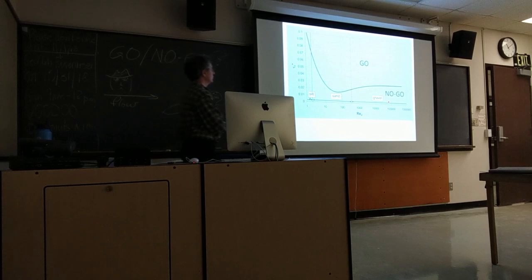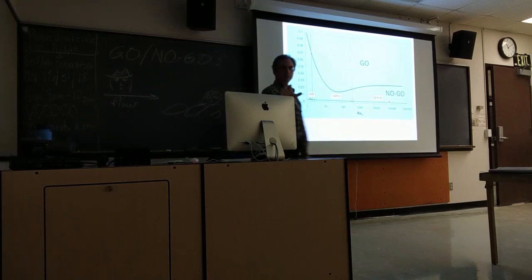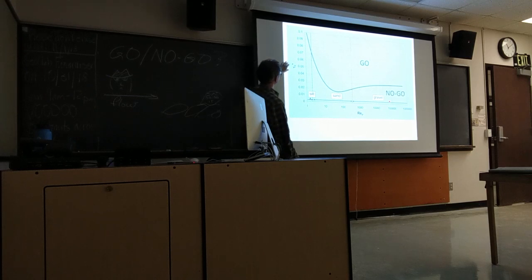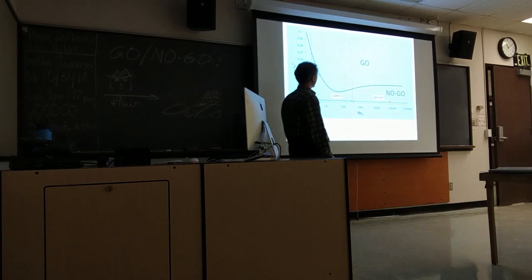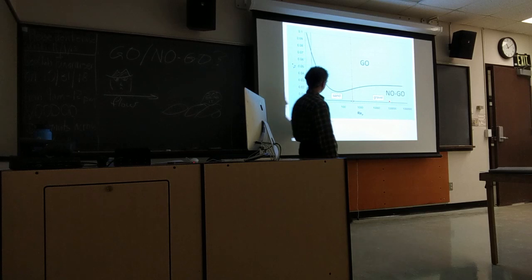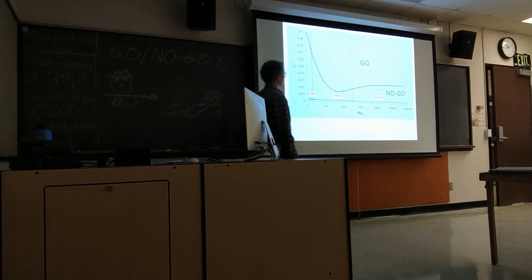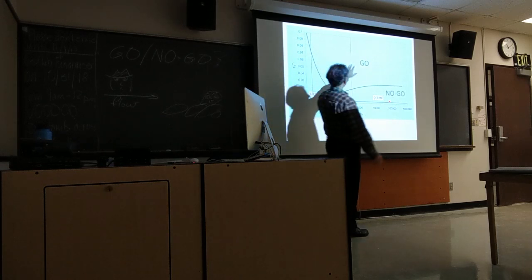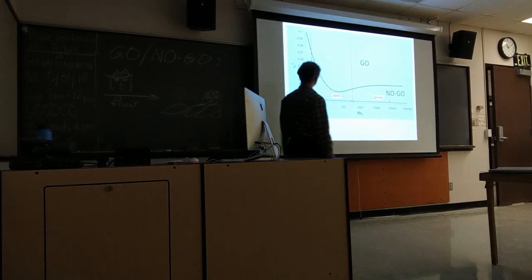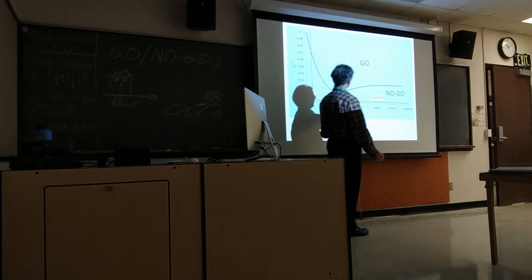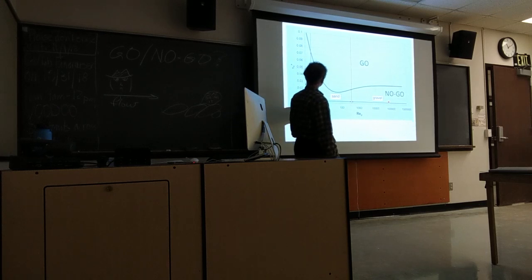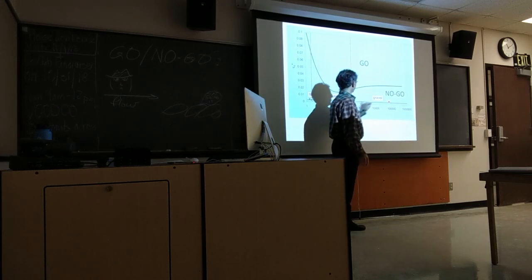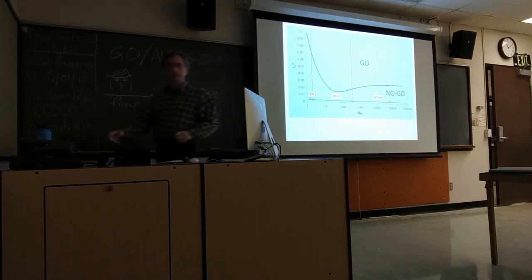This is a modified Shields diagram. And here we see this is labeled tau c star because there's only the one thing graphed on it. Well, sort of. And here labeled Re sub p for particle Reynolds number. The different sectors of the graph are labeled go and no go, and there are indications of at least rough size ranges for particles. That is, way down here we've got silt sized particles, and here we've got sand sizes, and up here we've got gravel and larger sized particles.